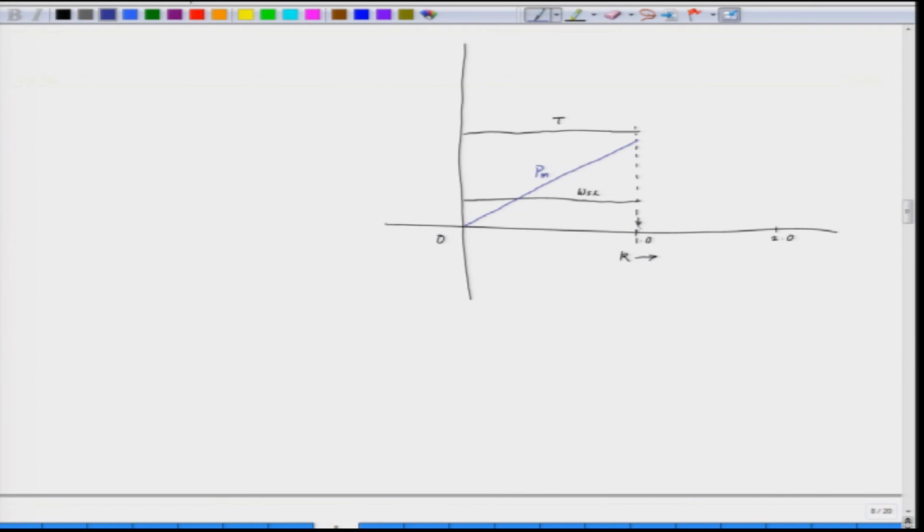And after the rated frequency, what do we have to do? We have to increase the slip speed. So, slip speed is increased to maintain the current constant. Now, if we see the current here, the current in this case has to be maintained constant. This is IS, the stator current.